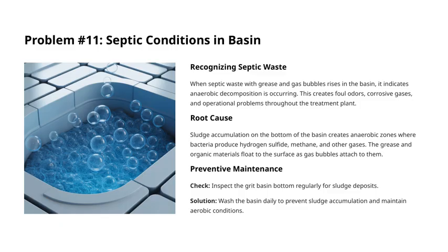Now, let's look at the root cause. Sludge builds up at the bottom of the basin, creating anaerobic zones. In these zones, bacteria produce gases like hydrogen sulfide and methane. At the same time, grease and organic materials float to the surface, attaching to gas bubbles.